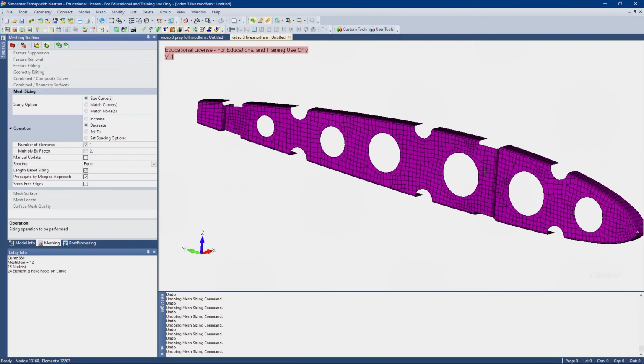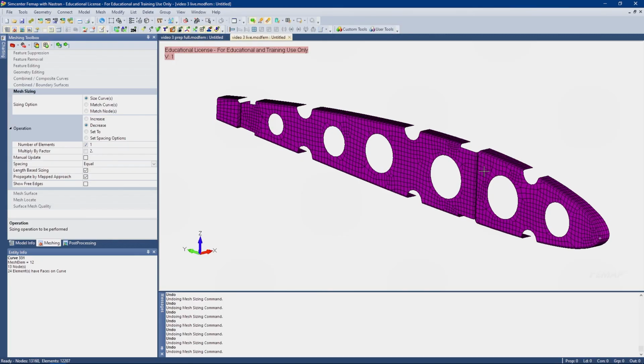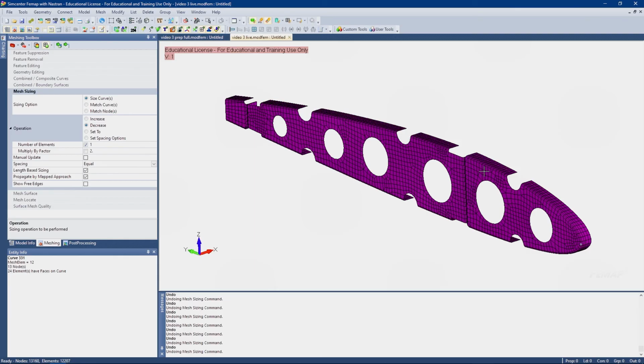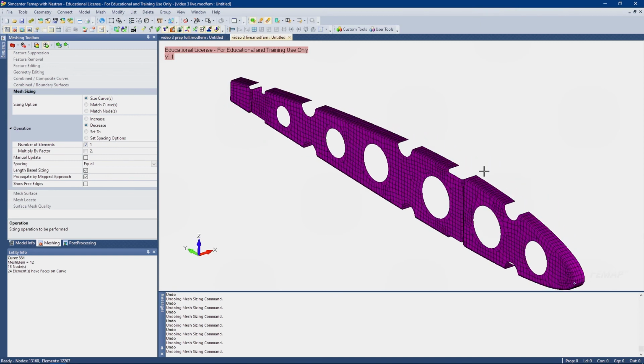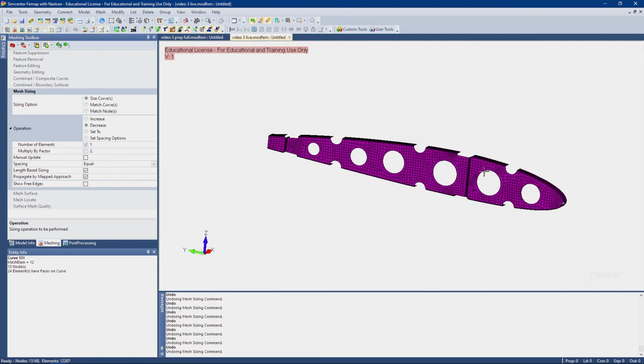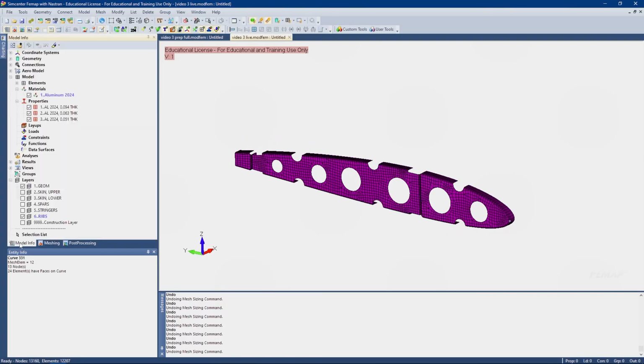good enough, and it'll be certainly stiffness accurate, and the stress will be mostly accurate, except in a few problematic areas. And if you encounter those areas in your mesh as the high points in stress, then you can always remesh and rerun to make sure that you're getting the accuracy that you need. But this isn't too terrible. It's workable. So let's continue on here.